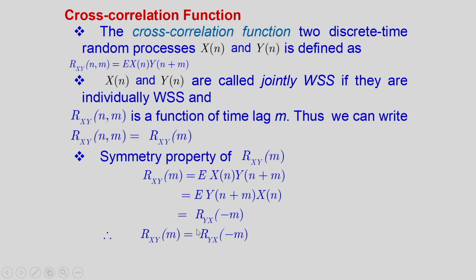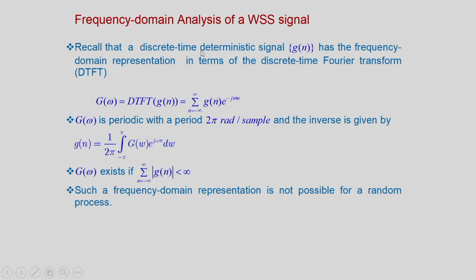So, if these signals are jointly WSS, then we can characterize them with the help of the autocorrelation function and the cross correlation function. Frequency domain analysis of a WSS signal. We know that in deterministic signal processing, frequency domain analysis plays an important role. We will see if a similar representation is possible for a WSS signal.